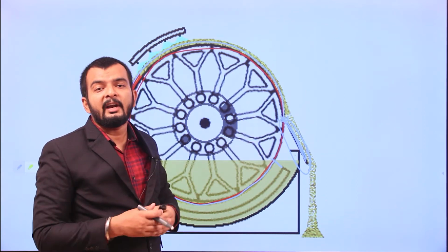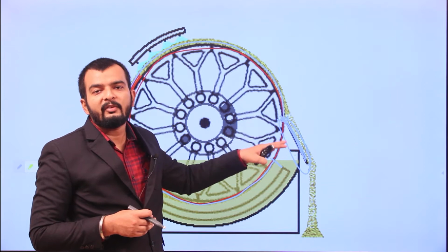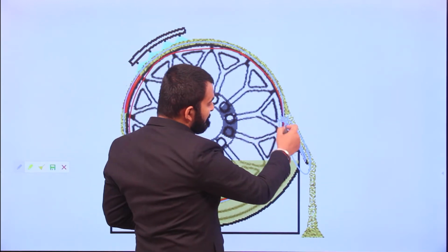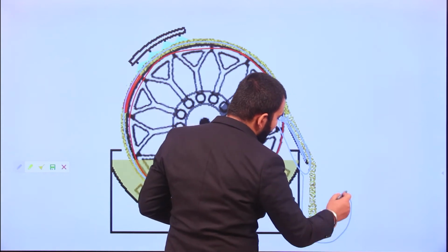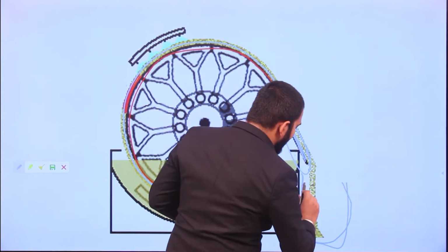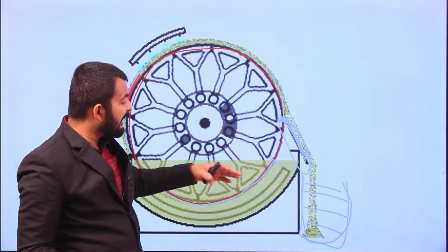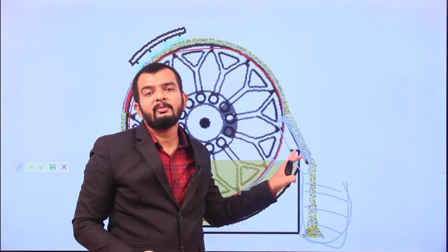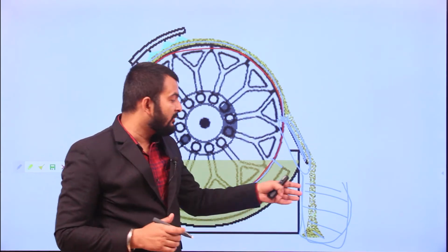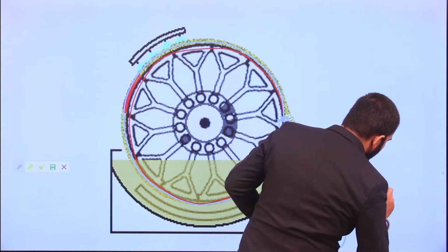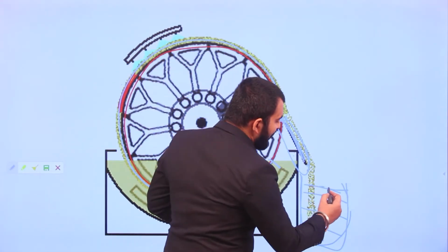Since we are using an inert surface, the removal of this dried particle will also be very easy. With the help of this doctor's knife, this material can be scraped off and collected in a container here. Now there are chances that whatever dried film you are getting here will not give you exact powder. So this may further require grinding.